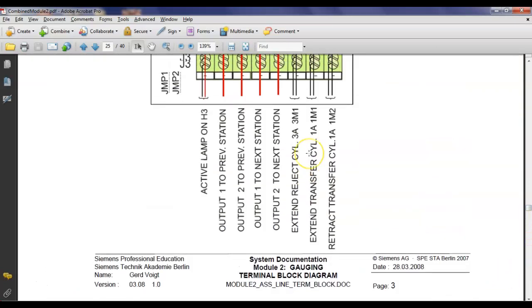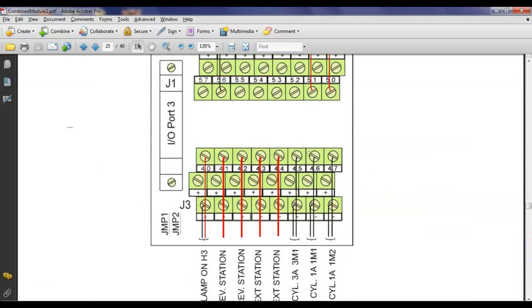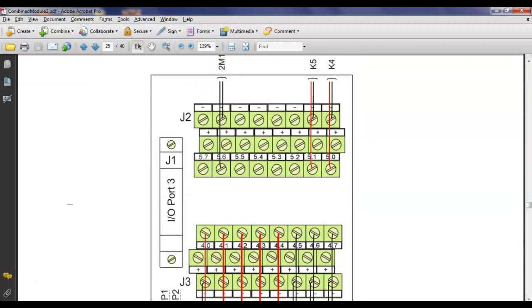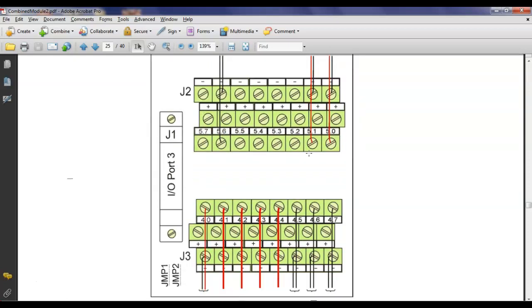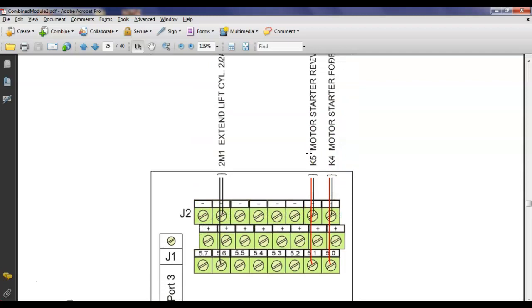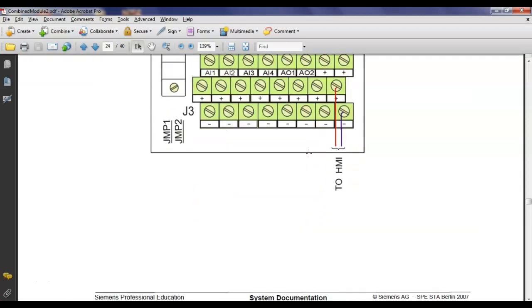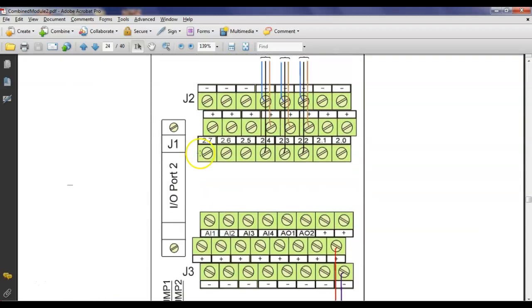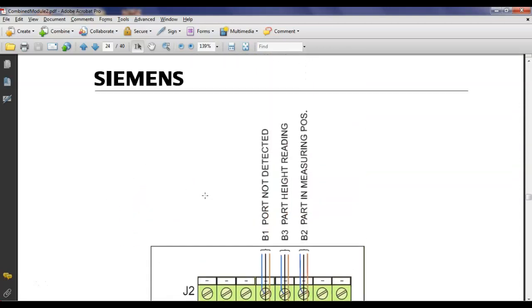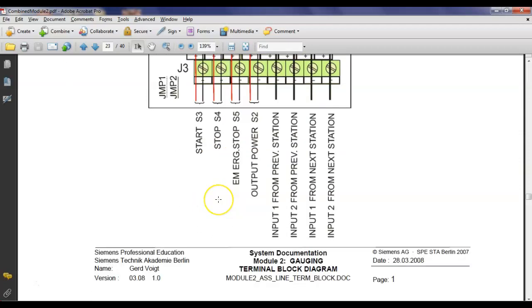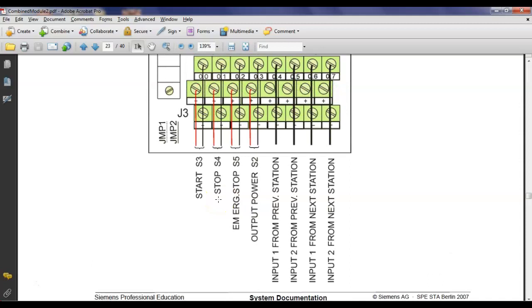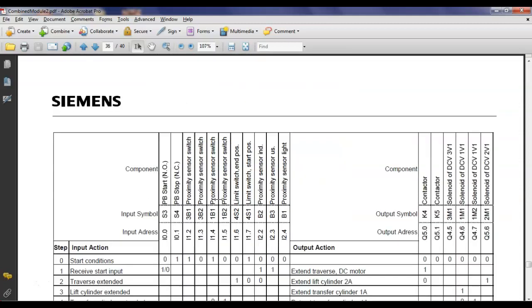And those are outputs, and those start on out. This shows you the wiring of the terminal block that the PLC connects to. So the PLC actually connects to these ports. So that might be a little easier. I don't think it's actually labeled on the terminal board itself.